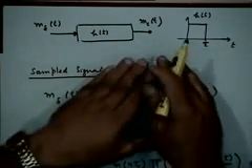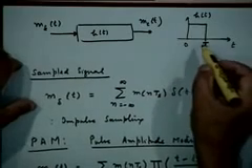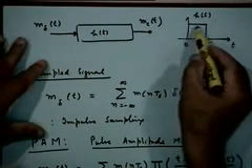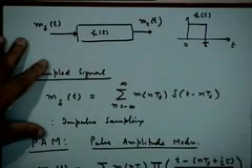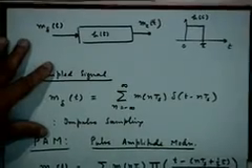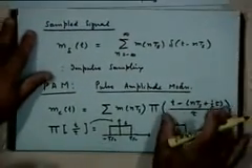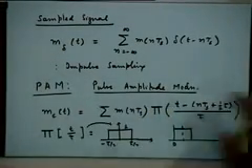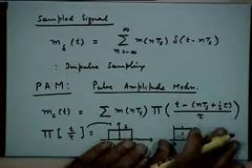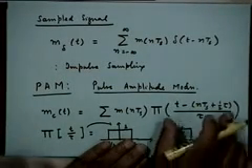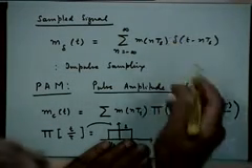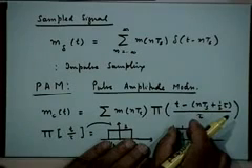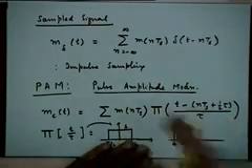So, you will have to first have a receiver filter which will have the inverse transfer function, right, which will cancel the effect of this pulse broadening that you have carried out, the pulse holding. You have done a sample and hold kind of operation here, right. Of course, you are not holding till the next time instant, but till the next pulse, but you have done some kind of broadening of the impulse to a finite width pulse, right, and that modifies the spectrum.